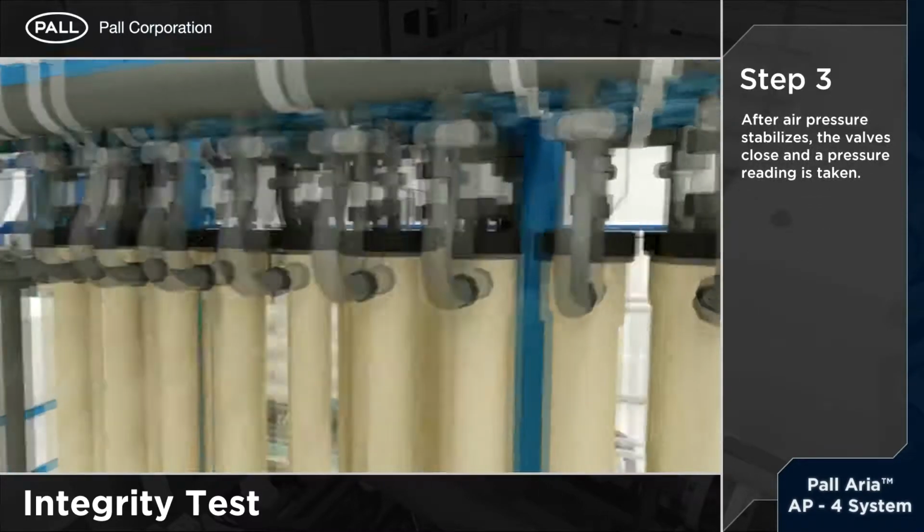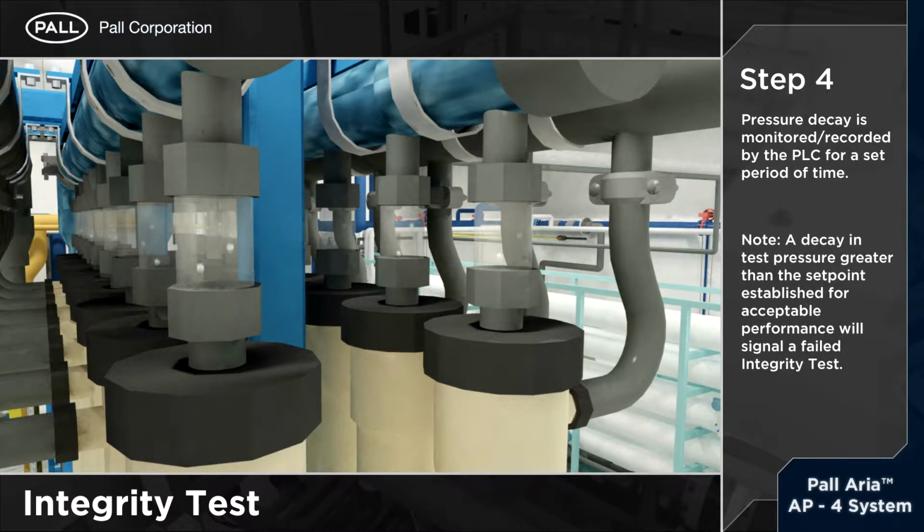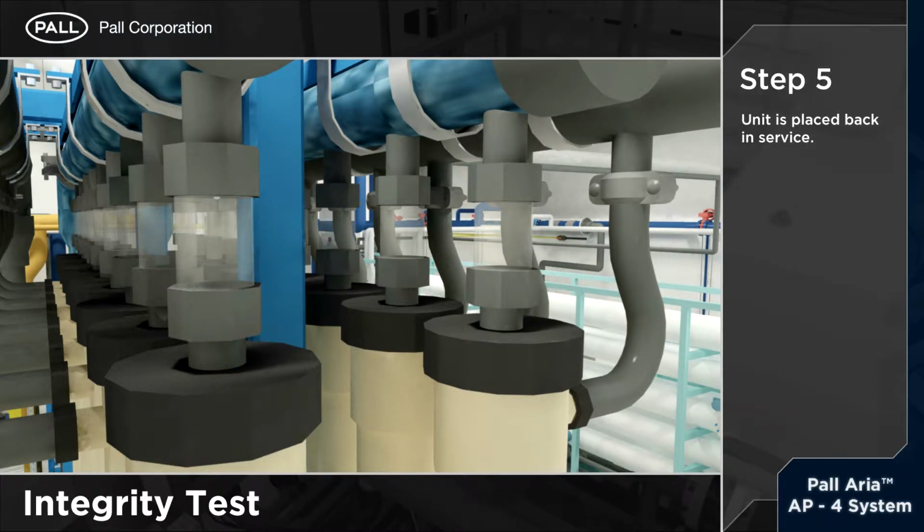After the air pressure stabilizes, the valves close and a pressure reading is taken. Pressure decay is monitored and recorded by the PLC for a set period of time. Please note a decay in test pressure greater than the set point established for acceptable performance will signal a failed integrity test. The unit is then placed back in service.